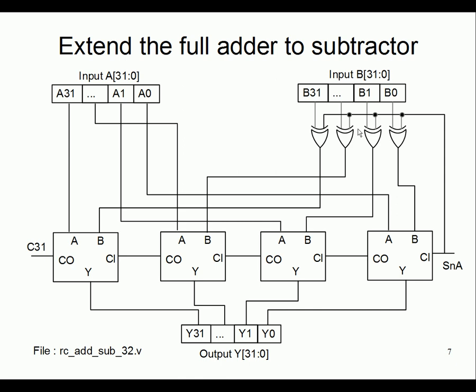The advantage of that is this is a very stable solution, guaranteed to work, because it's a matter of connection. If it doesn't work, you just need to debug the connection. Probably you made some wrong connection from one component to another. That's all the problem that can come in this type of gate level description.